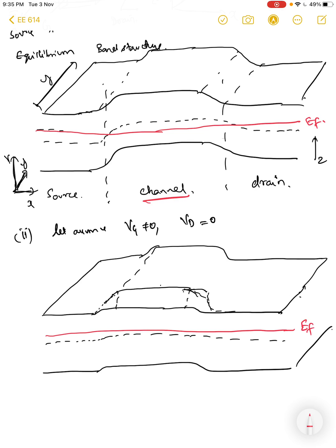At the surface, you have a slight dip in the potential space. The conduction band in the p-type semiconductor has reduced a bit because of the applied potential, and you have the EI in the p-type semiconductor lower than the Fermi level. So you have an electron concentration at the surface of the silicon-insulator interface. So this is at equilibrium.